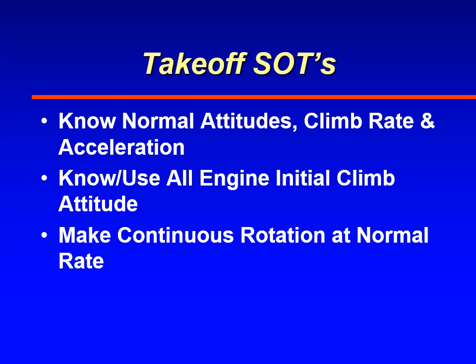And if anything is unusual, if you have a very high thrust setting and a very low airspeed, and the airplane is not climbing but descending, you know something's wrong. So follow standard operating techniques, and when things are not standard, when things are different, then you know that you are perhaps encountering shear.